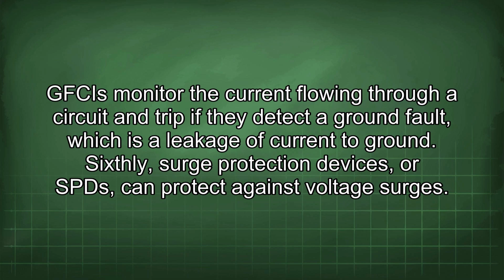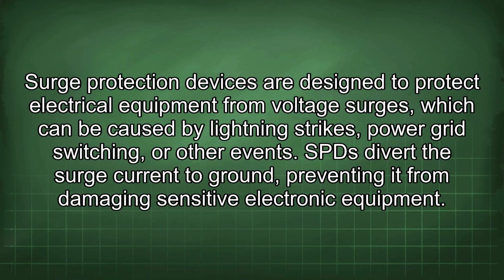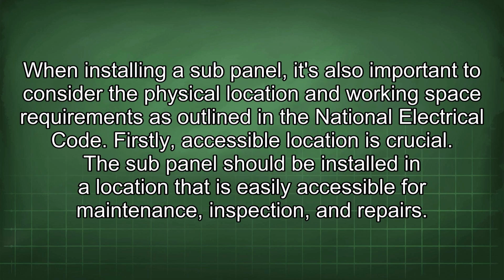Sixthly, surge protection devices, or SPDs, can protect against voltage surges. Surge protection devices are designed to protect electrical equipment from voltage surges, which can be caused by lightning strikes, power grid switching, or other events. SPDs divert the surge current to ground, preventing it from damaging sensitive electronic equipment. When installing a sub-panel, it's also important to consider the physical location and working space requirements as outlined in the National Electrical Code.